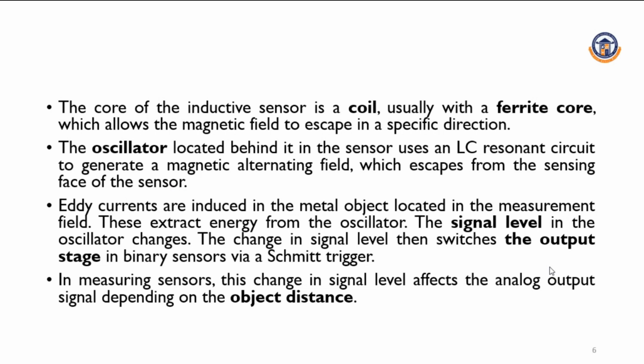So basically this inductive sensor is used for measuring metallic objects, and it will not be used to measure plastics because the induction of eddy currents will be done only inside the metal object. Next, we will go with the advantages and disadvantages of this inductive sensor.